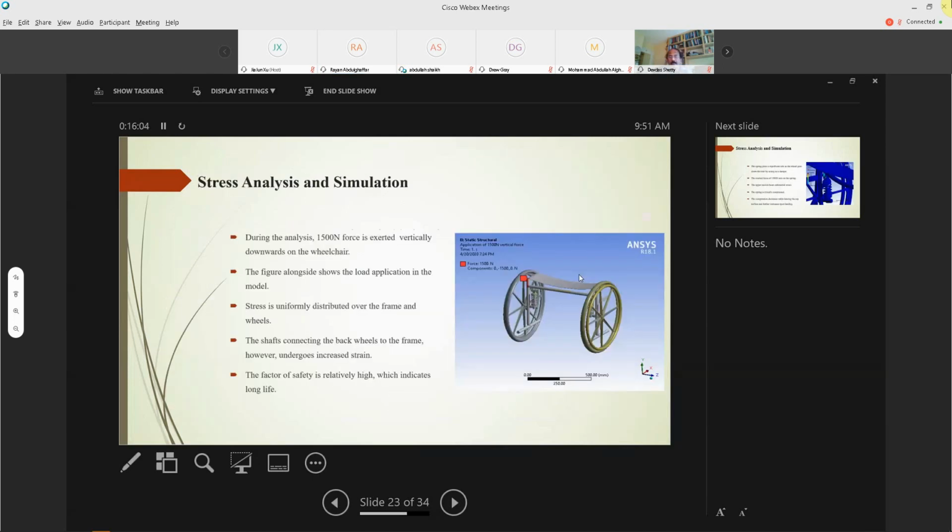For simulation in SolidWorks, we have done three scenarios. The initial performance analysis looks at the outcome when the wheelchair carries somebody. The first scenario is when the wheelchair carries somebody on a sidewalk. To complete this analysis, the model was subjected to 15 forces to determine the elementary stress allowance, and the figure indicates the specific location where the downward vertical forces are applied, as you can see.